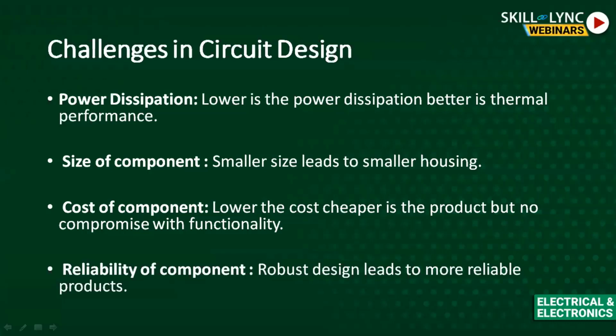And this is how products are validated in an industry where companies spend a huge amount of money validating a component against its thermal parameters, and then against different environmental factors, where you have rain, and thermal shocks, where your product goes from a high temperature range to a low temperature range, and then different kinds of ISO pulses which range beyond the product specifications. So products are rigorously tested, and that's the reason this is a very capital intensive industry.